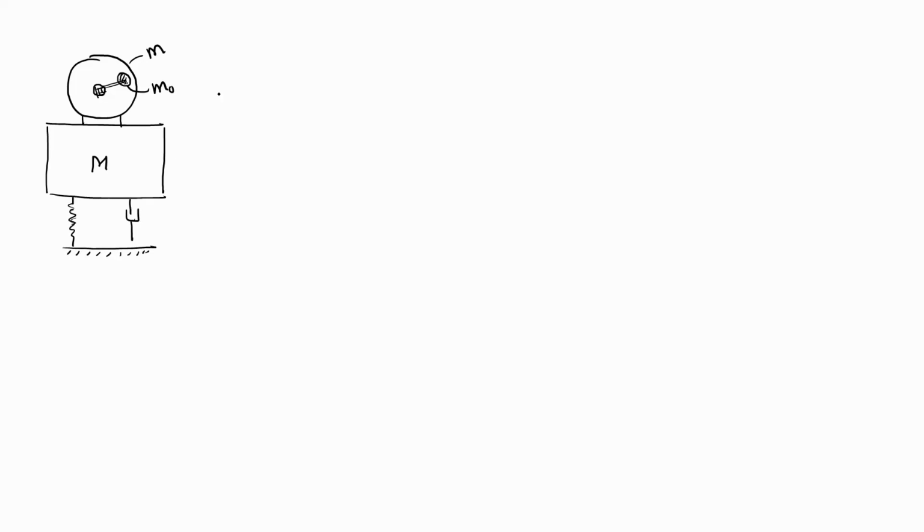So for the natural frequency, we need to consider this complete setup as a rigid body, which is mounted on this spring and damper. So total mass, I will write here, mt is equal to mass of the platform plus mass of the motor plus eccentric mass m0. So the given data is the mass of the platform, that is capital M, equal to 5.16 kg.